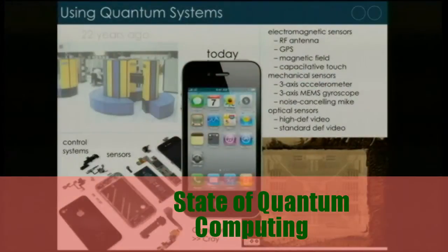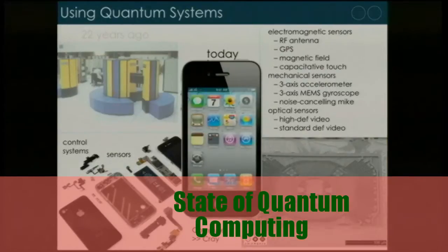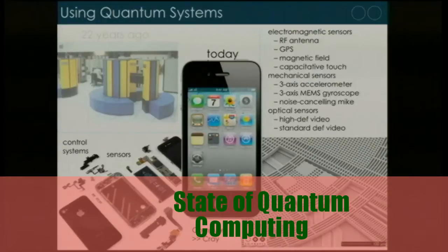And if you zoom in on some of those sensors, they occupy length scales that are really quite small, microns or fractions thereof. So here are some pictures of the mechanical accelerometers that sit inside an iPhone and let it measure accelerations. As you zoom in on them, you see these incredibly small structures. Here's 100 micrometers, so that's 10 to the minus 4 of a metre. So these things are at the scale of 10 microns.